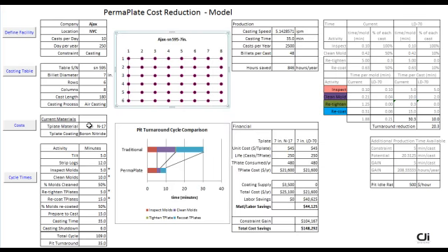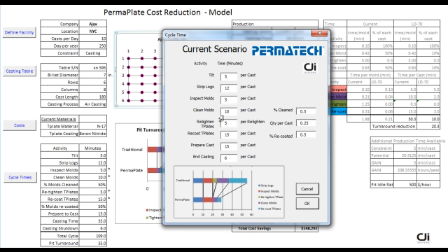So we now have established this information, and then we establish what the actual cycle times are for the pit turnarounds. There's a tilting operation which is fixed in any plant. You have to pull the logs. Then there is a variable amount: the inspection of the molds, the cleaning of the molds, retightening of T-plates where needed, and then recoating T-plates or redressing them, and then prepare the cast and then set up for the next cast. All these together typically can add up to an hour.